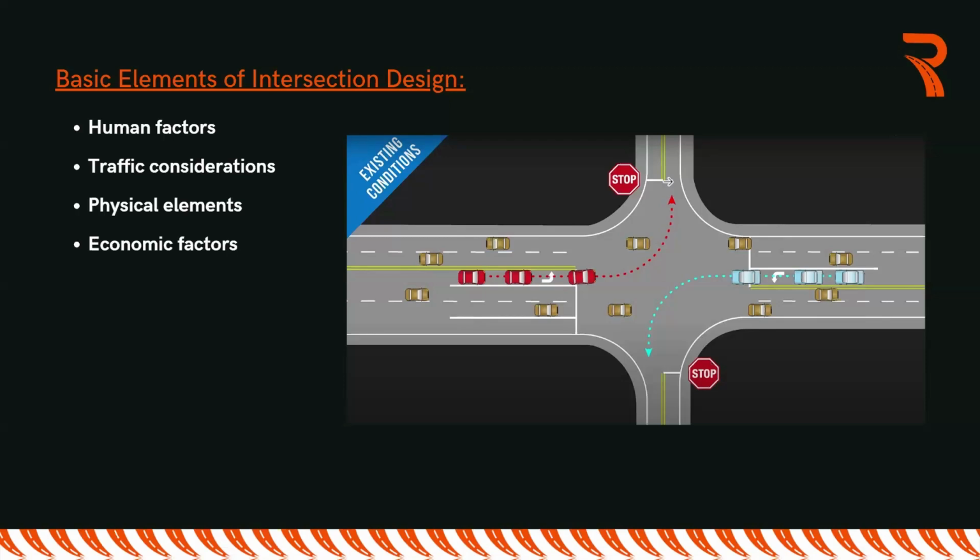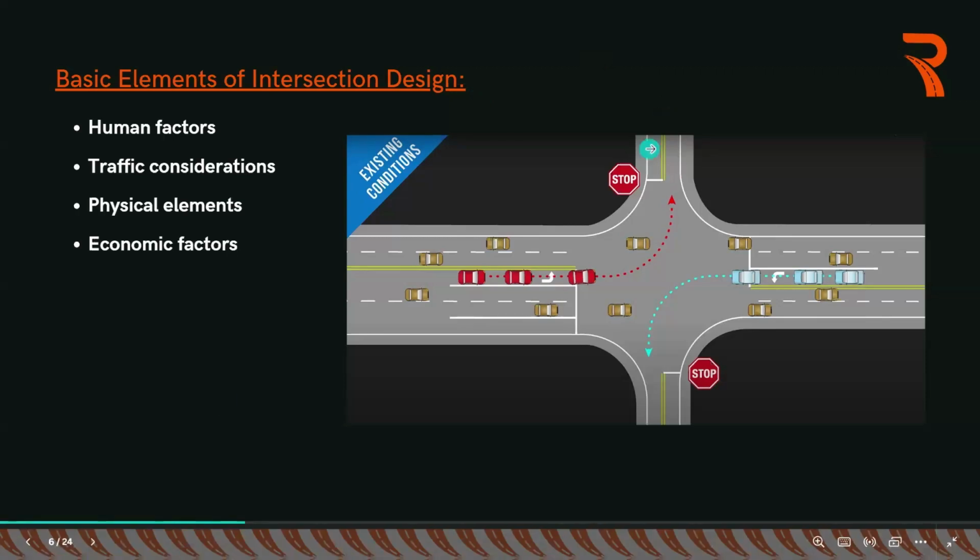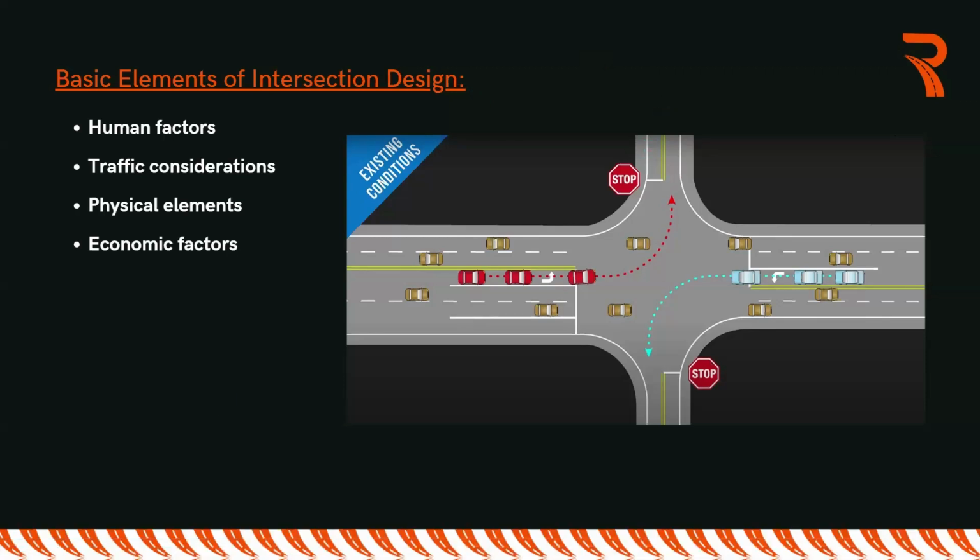Then we are talking about the capacity of our intersection. You need to carry out a traffic survey so that you know the expected capacity here and the projected traffic growth in 10 years from today. Of course, for those of us who have done traffic calculations, you have taken into consideration how to project traffic growth.